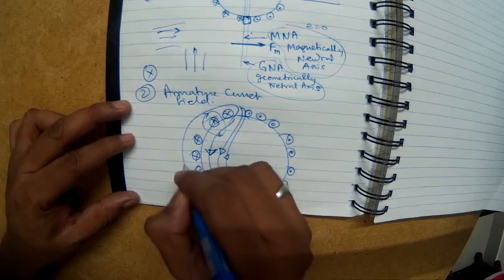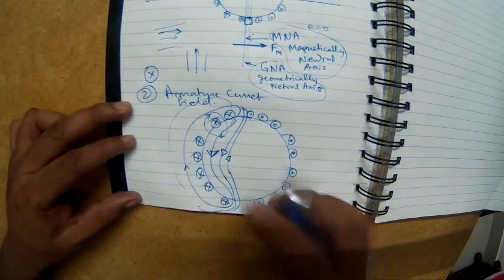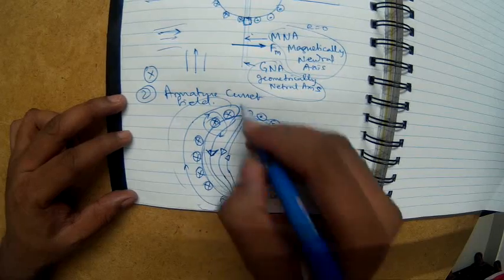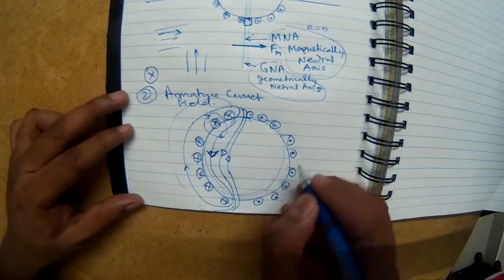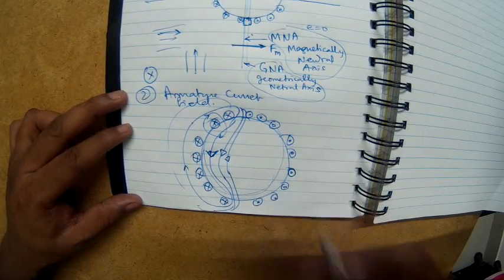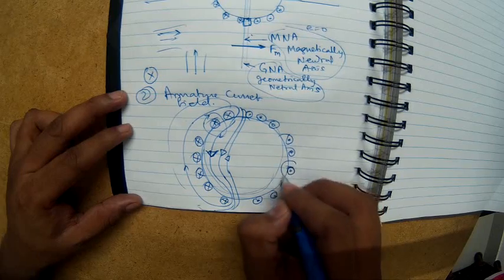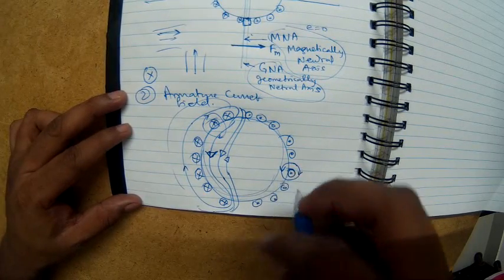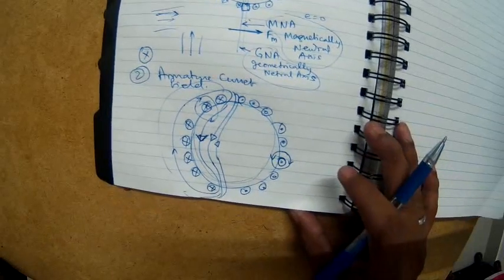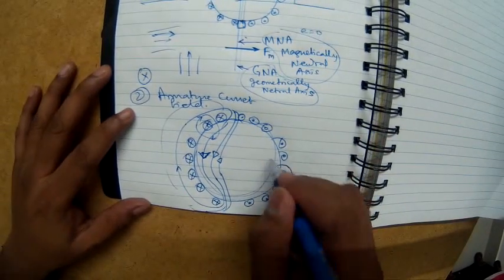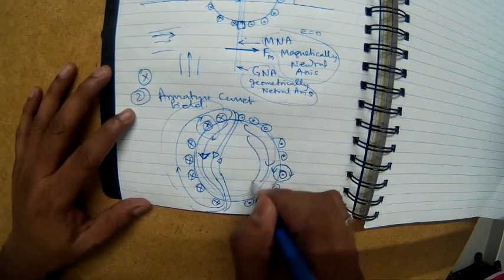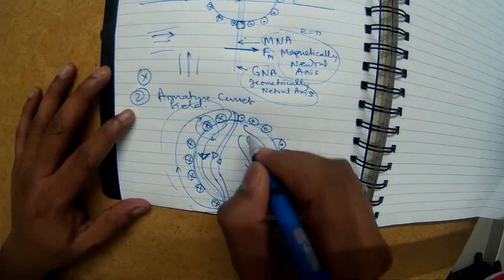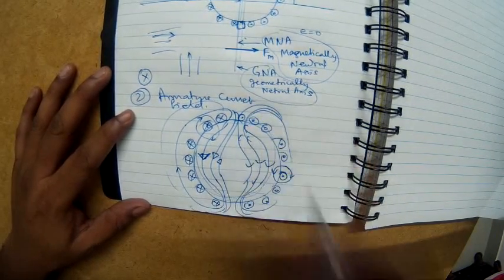So of course this joins from the outside. If you focus only on the armature, the magnetic field is going downwards in the armature. Similarly, look at this. Here the current is coming out of the field, so the magnetic field will be like this, because using the corkscrew rule, you can again find the direction that way. And if you want to find the resultant field, it will be something like this. So this will pass through the windings like this.